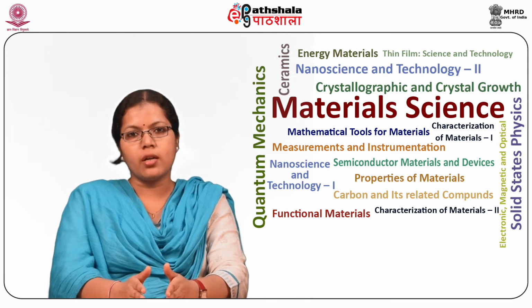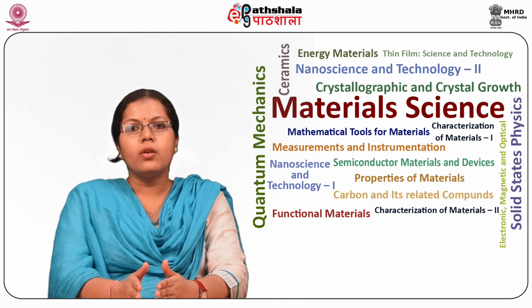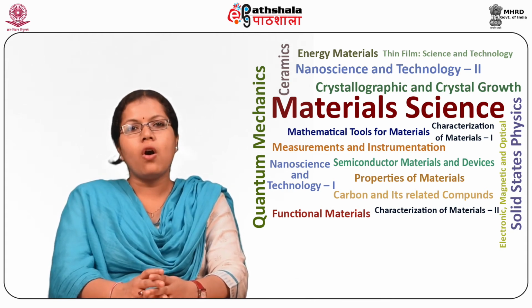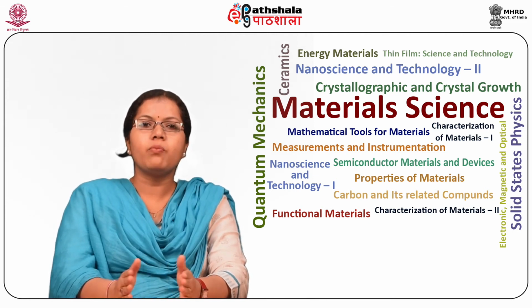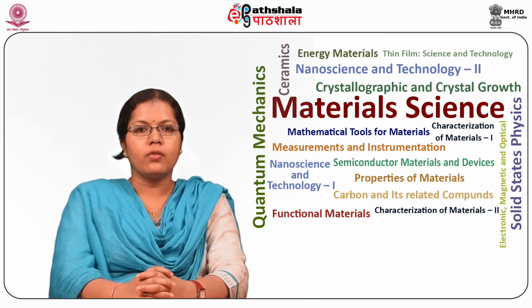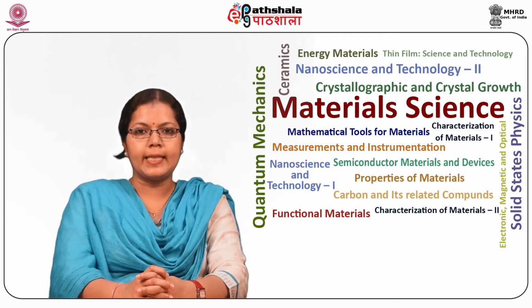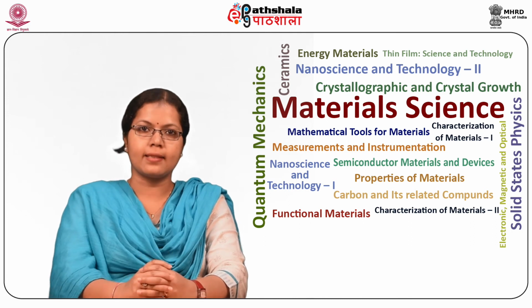The universal shunt or add-on shunt is used for multi-range ammeters. The advantage of a universal shunt is that it eliminates the possibility of the meter being in the circuit without a shunt. But this advantage is gained at the cost of a higher meter resistance.